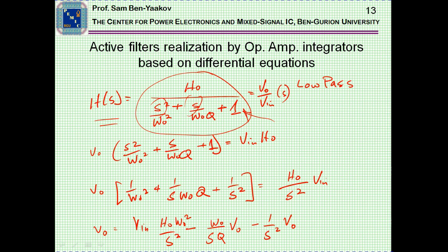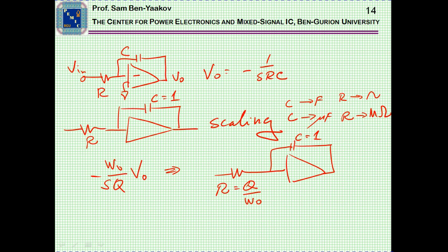And what we do, we like first of all to express it as a function of V out, and we have the various elements here, which is just another way of expressing the relationship between the input and output. In this approach, we are using integrators. Integrators are really nice because they smooth out noise, so they are very good in terms of noise performance.